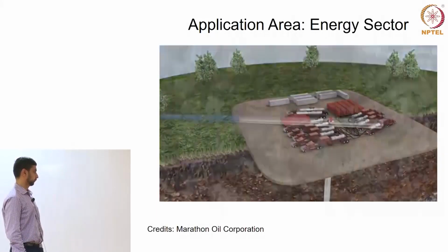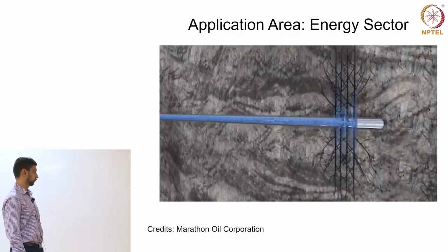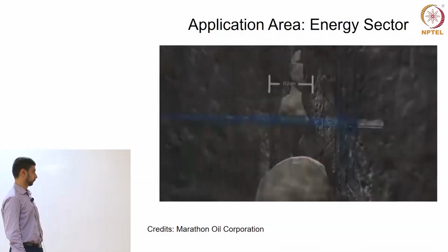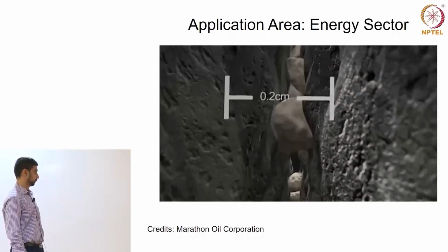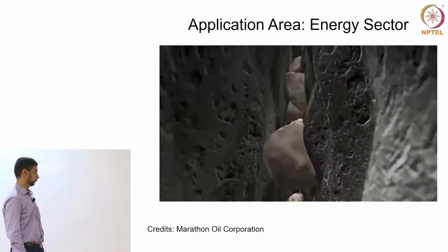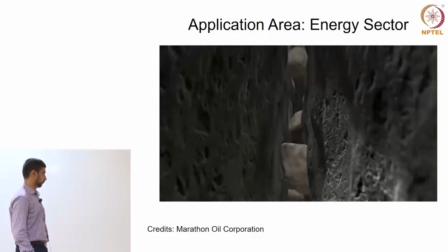This process creates fractures in the oil and gas reservoir rock. The sand in the frac fluid remains in these fractures in the rock and keeps them open when the pump pressure is relieved. This allows the previously trapped oil or natural gas to flow to the wellbore more easily.